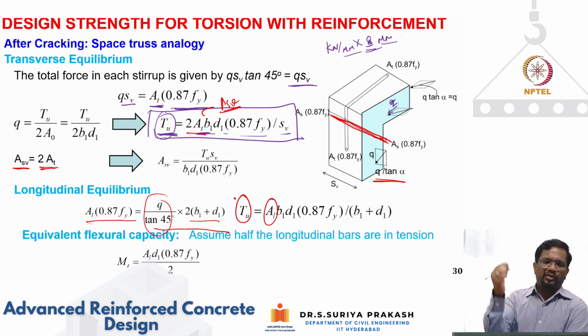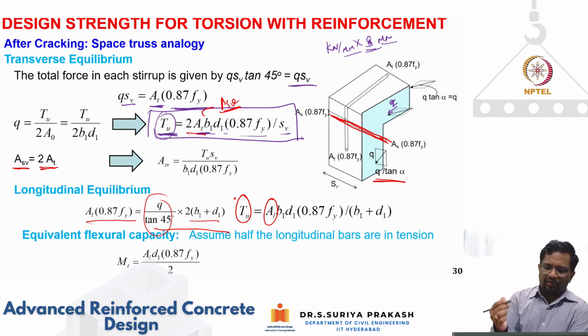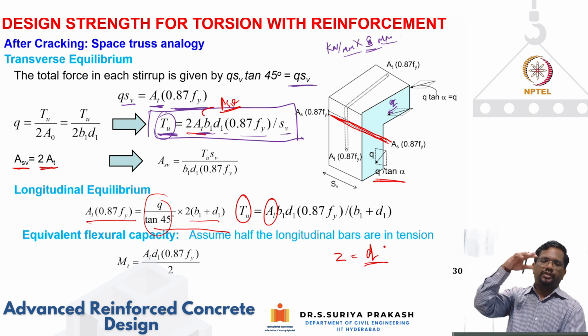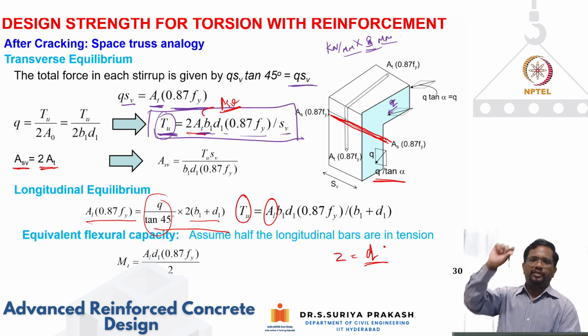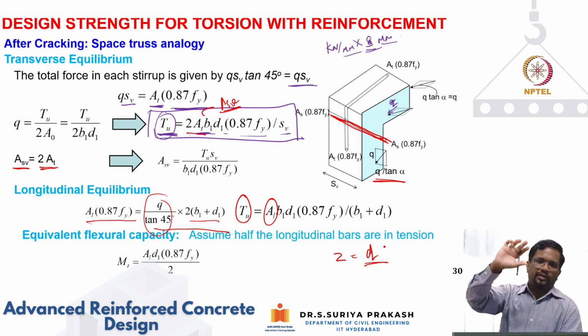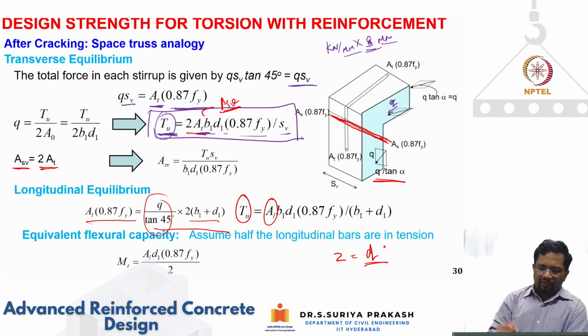And we know that for an under reinforced section, my lever arm Z is going to be very close to that of your effective depth, right? For an under reinforced section, if you go back to a moment curvature analysis, we said 50 mm, 55 mm for a 600 mm. So you will find that the lever arm will be nearly equal to that of your effective depth.